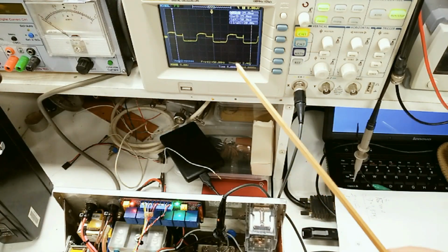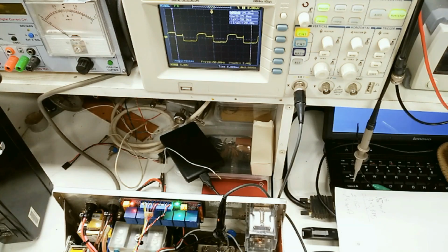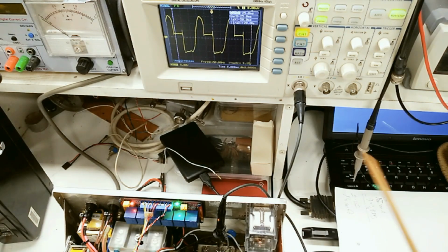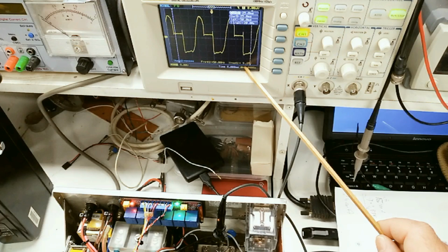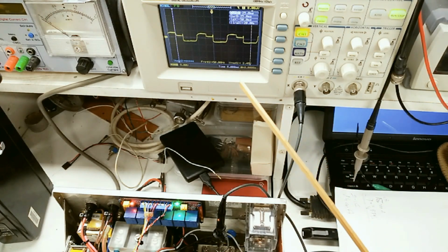Now the voltage drop is 2.47 RMS, and before it was almost 10 volts RMS. Now it's on the 360 ohm resistor. Actually now the voltage drop is 9.17 volts RMS. Now I short circuit the resistor and I get 2.45 RMS voltage drop. Now that's with no load.